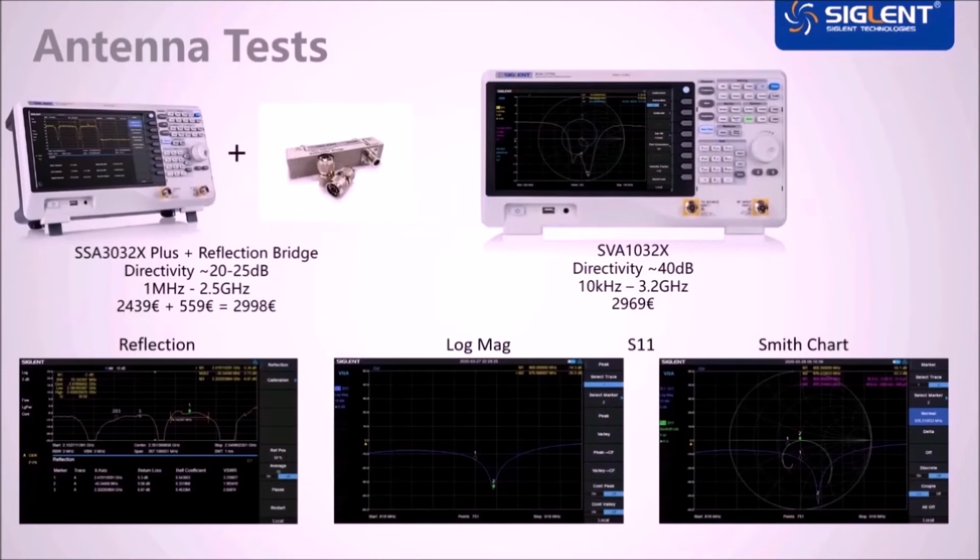The antenna test is the first test which I want to show you. Probably also the test that almost nobody can avoid, regardless whether you develop the antennas yourself or buy them. The impedance matching must always be checked. Basically, it's about how well the antenna input impedance matches the output impedance of the signal source. Basically, how much energy is reflected. Conversely, you can then deduce how much energy the antenna is emitting.